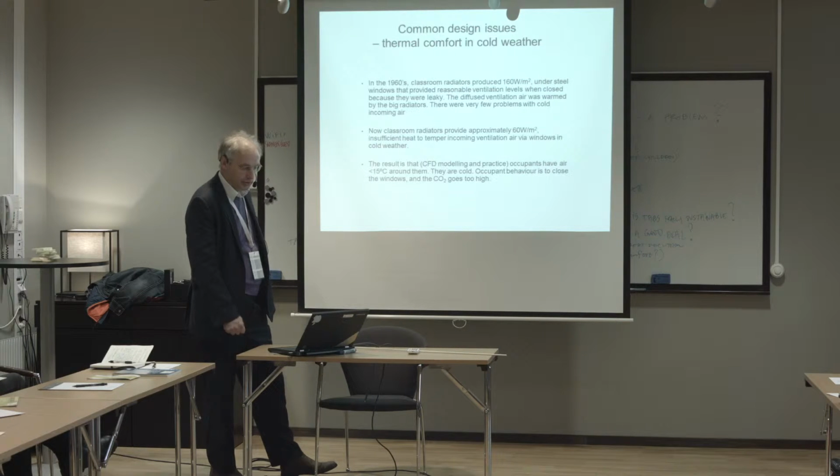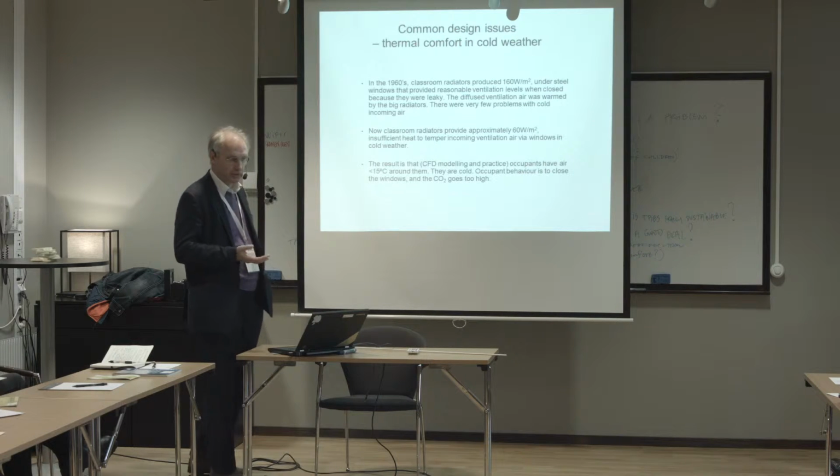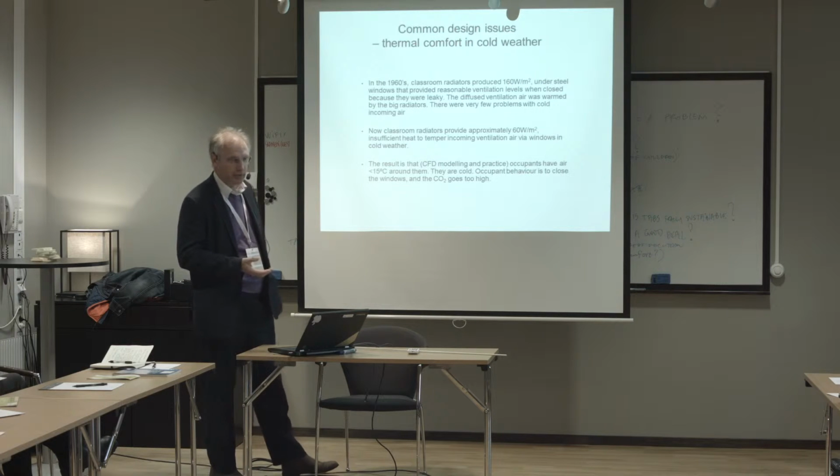And we've introduced a new guideline which says that the supply air, when it hits the occupied zone, must be at least 15 degrees in a classroom. That's 5 degrees below the normal environmental temperature of the room. And that's where I'm trying to say that the thermal comfort criteria like ISO 7730 would say that isn't comfortable, but I would maintain that that is comfortable for children.